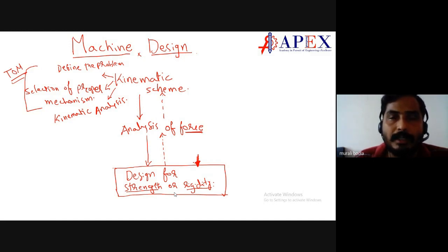So we need to minimize the losses. In order to do that you need to maintain certain rigidity in the component so that you can limit the angle of twist. And not only this, we might have discussed whirling of shafts, where after a load is applied in the center of a simply supported shaft, we have seen that it may deflect due to dead weight. So that deflection also we will limit, because as we've seen, one of the problems is the vibrational loads it can generate, and other thing is even in operation it creates other problems.